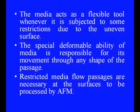Now, let us look at the principles of this abrasive flow machining process. In the AFM process, a semi-solid media is used which comprises a carrier in the form of a polymer base which contains abrasive particles in a desired proportion. It is extruded under the given pressure across the surface which is to be machined. The media acts as a flexible tool whenever it is subjected to some restrictions due to the uneven surface. The special deformable ability of this media is responsible for its movement through any shape of passage. This can be seen like this.